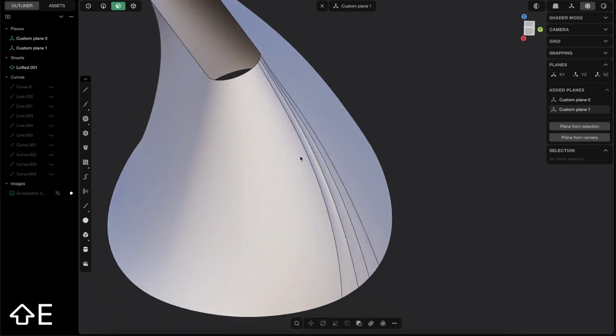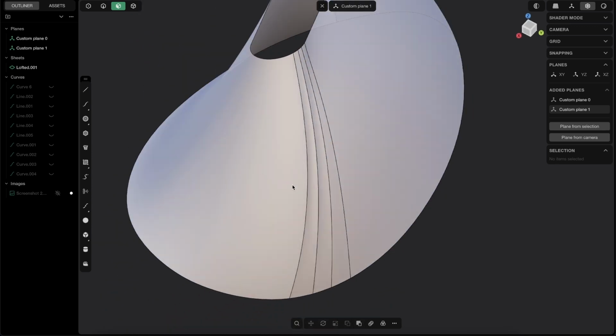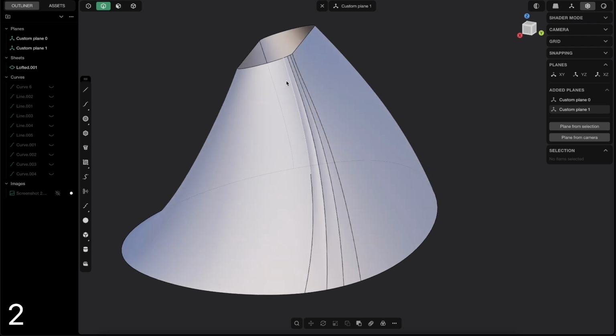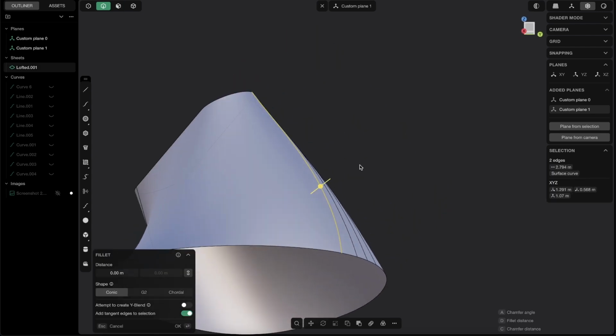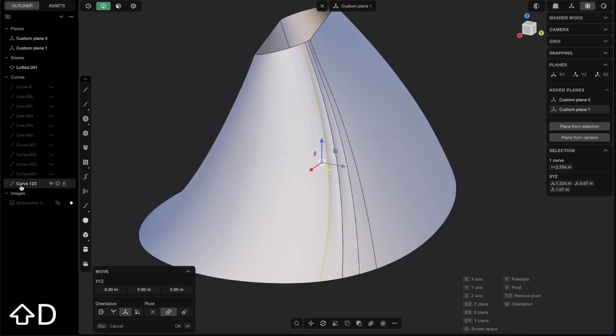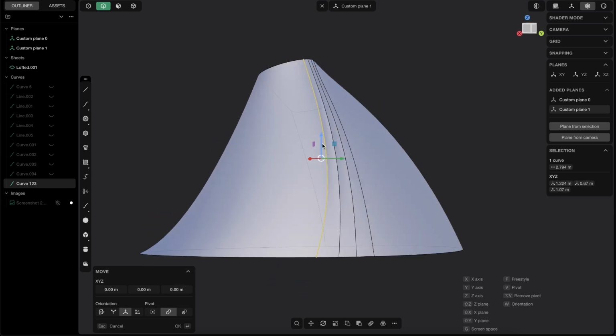And then come back to this video, and now press 2 and select this long edge, one by one, and Shift D to duplicate, so you have one curve, make sure it's one curve, and now we have to rebuild it first.